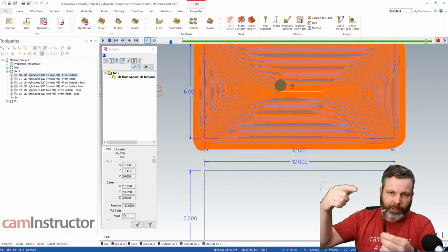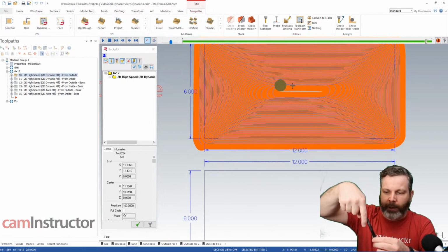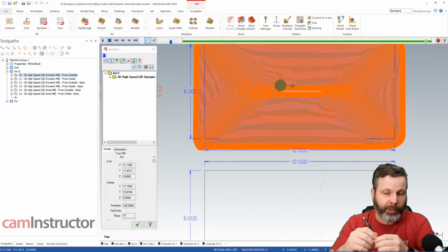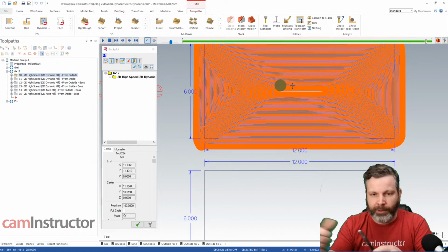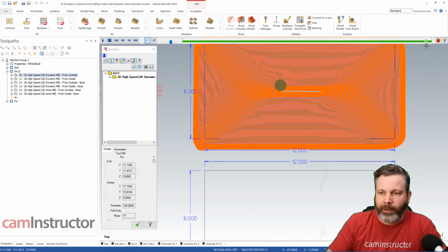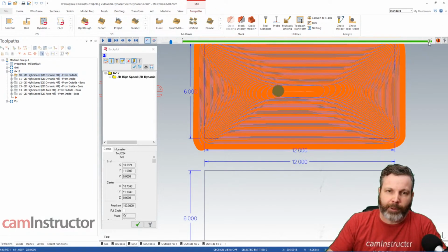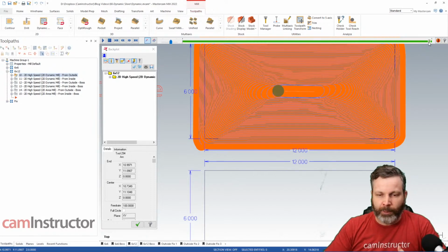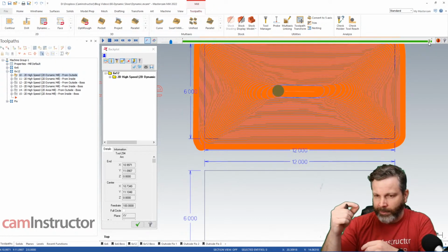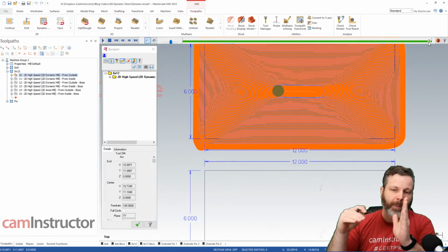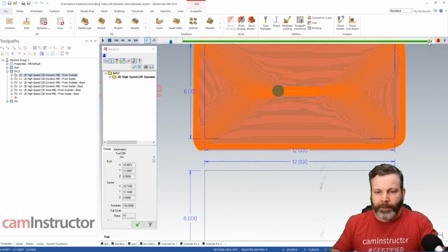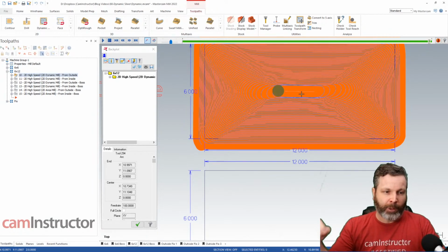Okay, so that's not a big deal until you come back around the other side, and all of a sudden this piece that's tipped over that you would have engaged 10% of your cutter into is now engaging 30, 40, 50% of material because it's deflected over. And that unexpected load on your cutter leads, obviously, to bad things happening. So when you're pushing a tool at its maximum, right in the boundary of breaking versus not breaking, and that's relative to that 10% step over, if you're now getting into a cut that's 20% step over, things are going to go bad. Things are going to break. So this is the problem that can come up with Dynamic Mill.